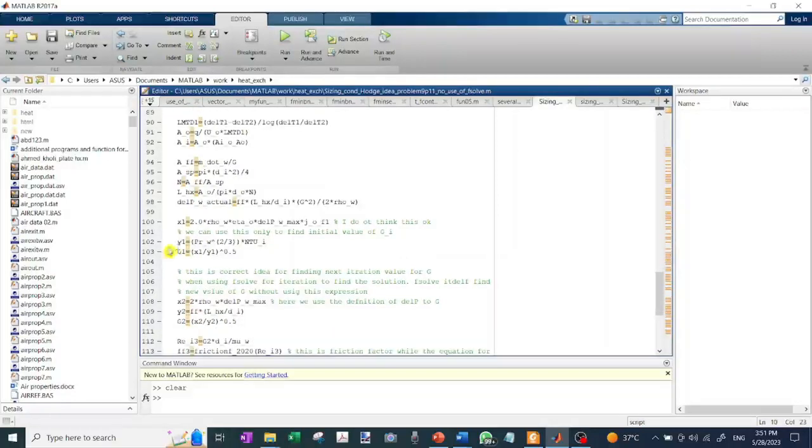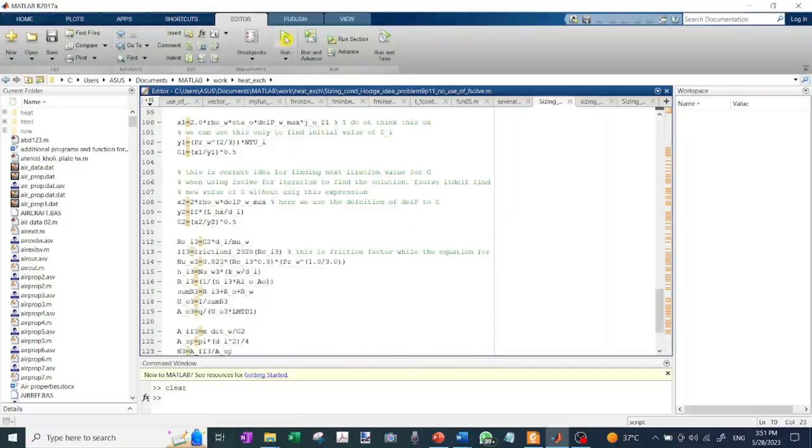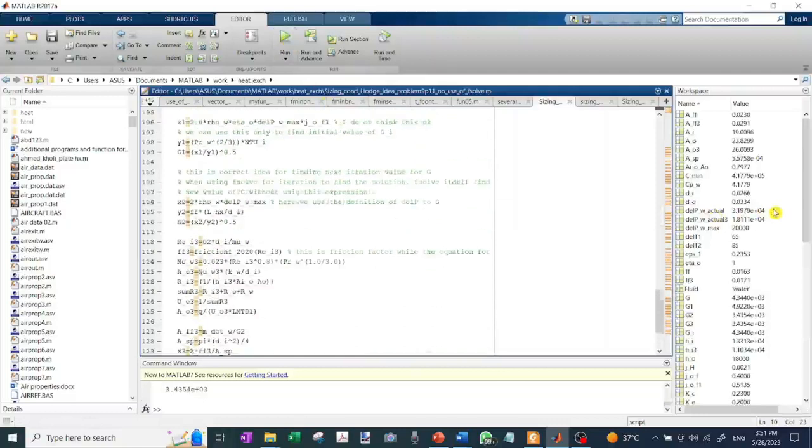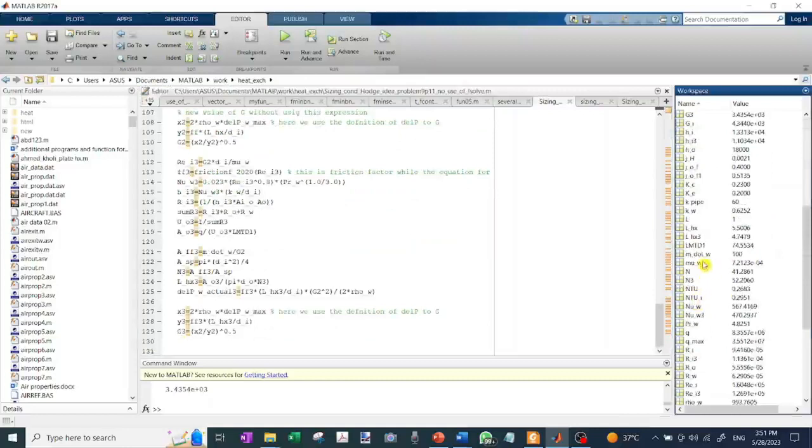required. And also we go to another value for G, using the result from the first initial procedure, and we find G2 and so forth. So when you run this, you get two iterations for finding the length and the number of tubes. If you go here, you'll find that L, the final value, is 4.74 meters, and the number of tubes is around 52